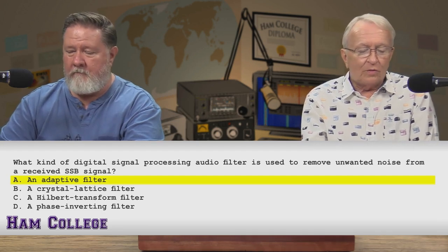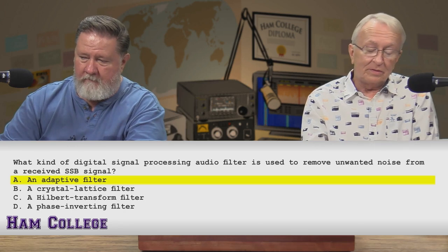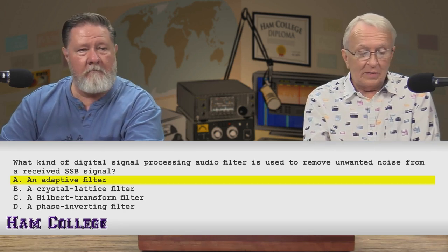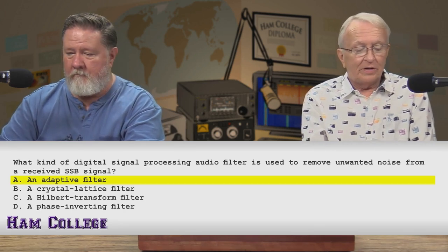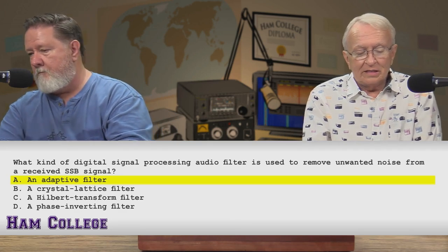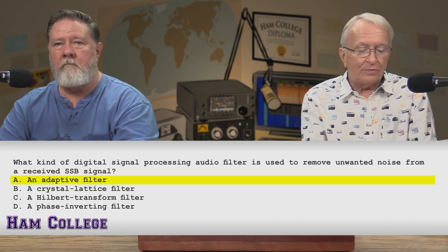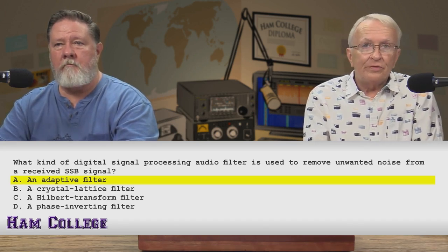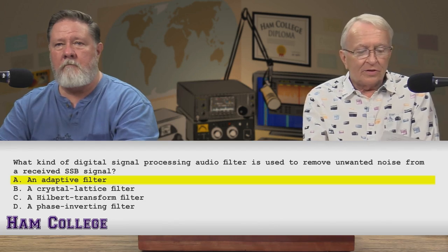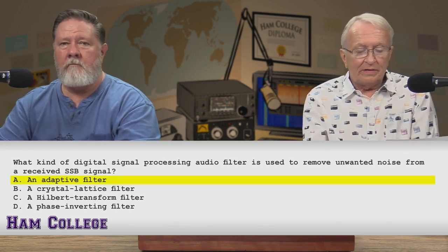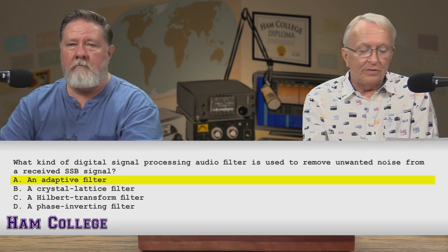One way to remove the noise is a filter with a notch, which I was just saying, at the mains frequency and its vicinity, but this could excessively degrade the quality of the ECG, since a heartbeat would likely also have frequency components in the rejected range. To circumvent this potential loss of information, an adaptive filter could be used.